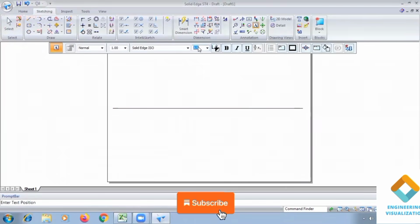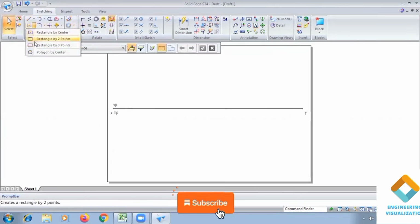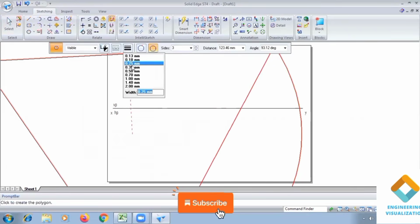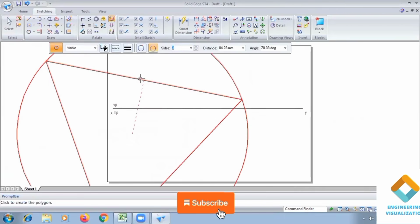So first I'll draw the XY line, writing HP and VP, since it is lying in the first quadrant. Go to polygon by center and select the number of sides as 3, and resting with respect to edge.